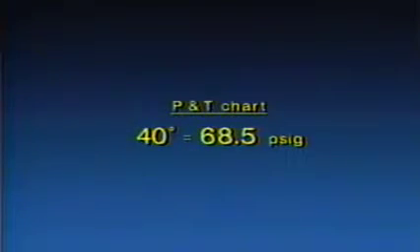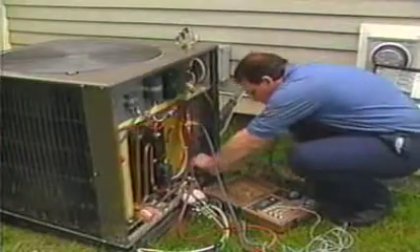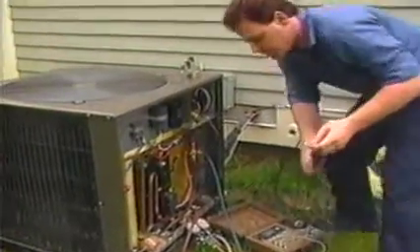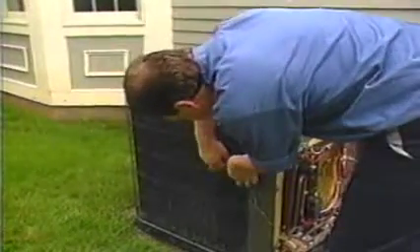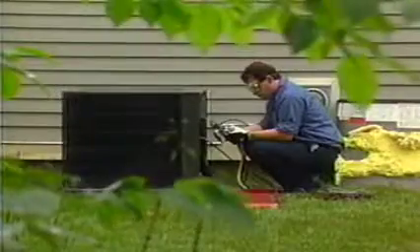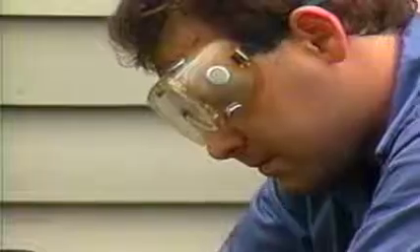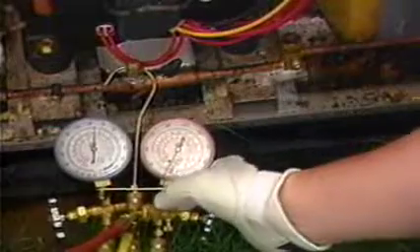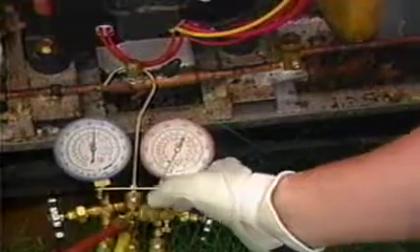The head pressure reading is 220 psig, very close to the calculations you have just seen performed. According to this information and the pressure-temperature chart, the design suction pressure is 40 degrees Fahrenheit. This would correspond to 68.5 psig on the P&T chart. Because the outside temperature is only 79 degrees, this unit does not have a heavy load on it. The head pressure is well below the design pressure for a 95-degree day. An estimation would put our suction pressure at about 63 psig. Our actual reading is 63 psig.